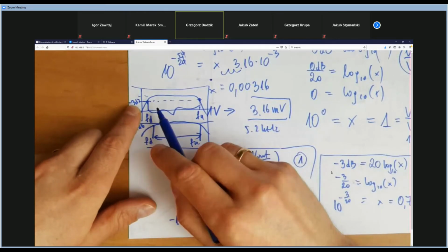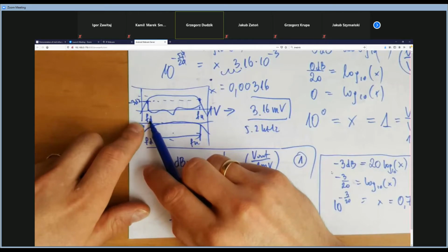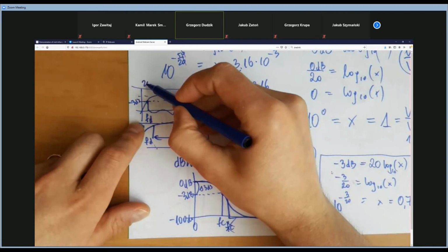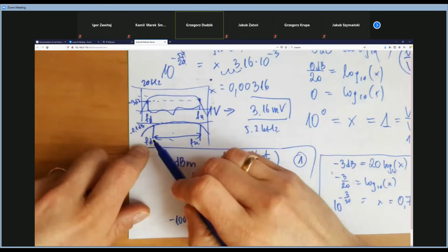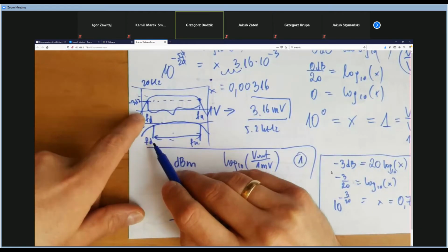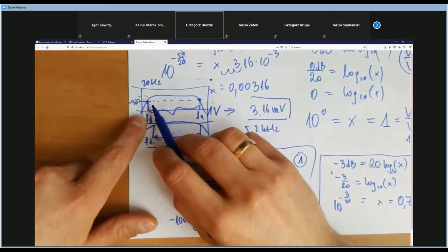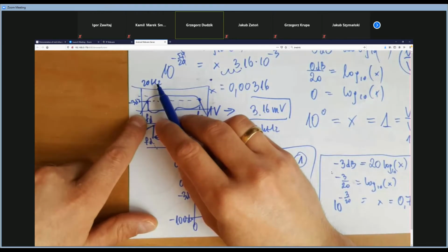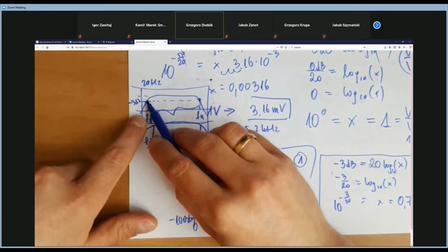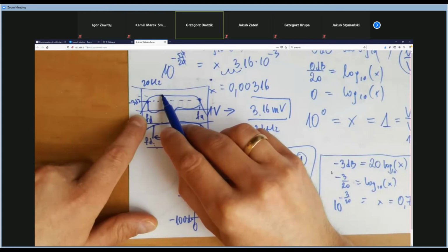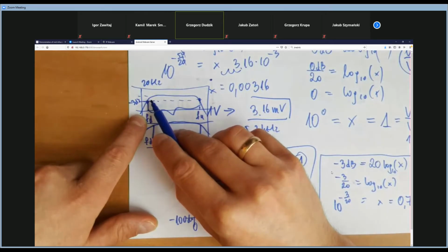Look, if the down frequency for the amplifier, for example, is specified as 20 hertz, for both hi-fi and the typical one, it means that for the typical amplifier at 20 hertz our output signal is decreased by -3 dBs. So the signal at 20 hertz is lower than the maximum signal by 30%.